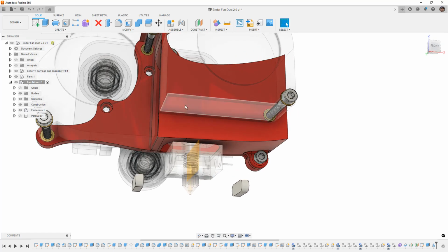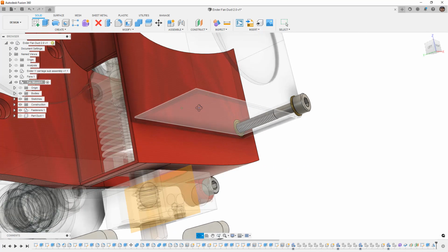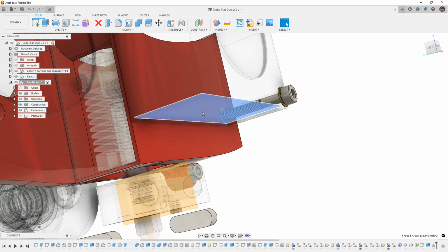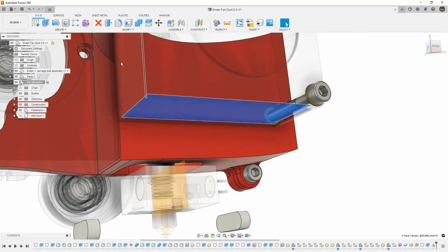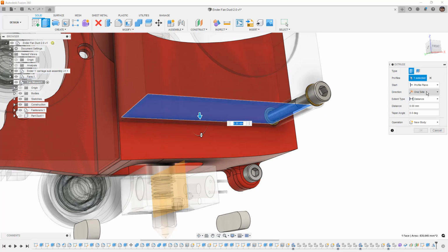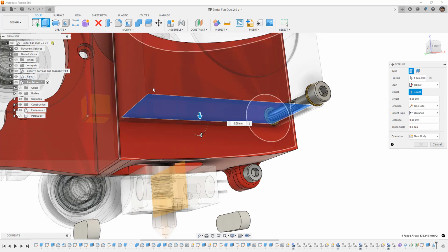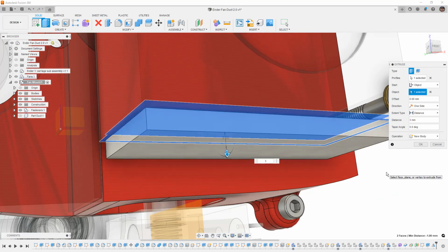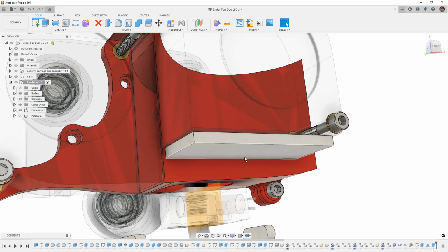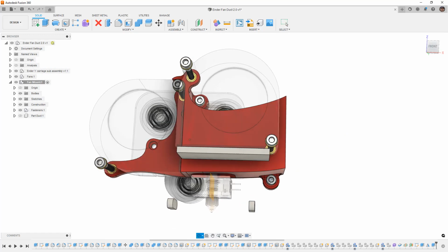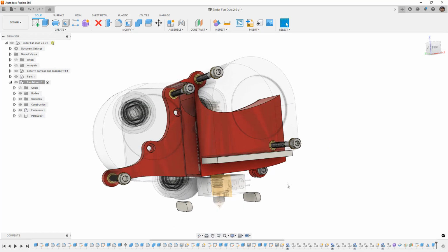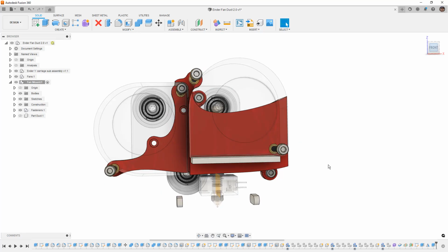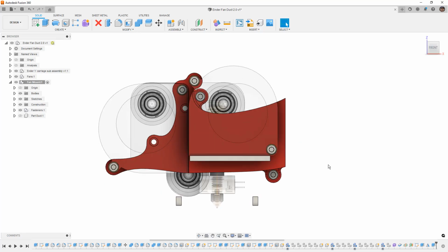Next, I want to build out the outlet, which is essentially the inlet for this duct system from the fan. Now, the way that these work is there's a small recess here. So I'm just going to select that face, and I'm going to hit extrude. But I want to extrude it from an object. So I'm going to take, there's a little exterior lip here. Then I'm going to extrude it 3 millimeters, just like the end pieces that are pointing at the nozzle. So this gives me the geometry I need to connect. This is my starting point in 3D space.